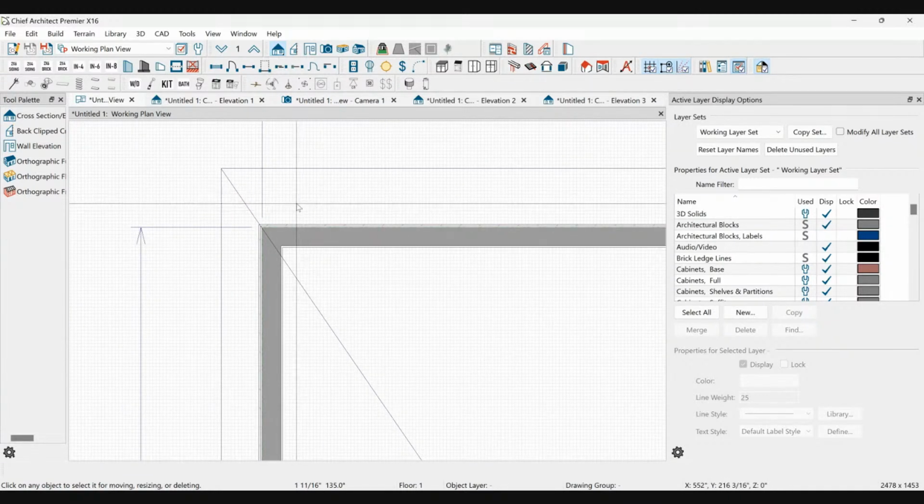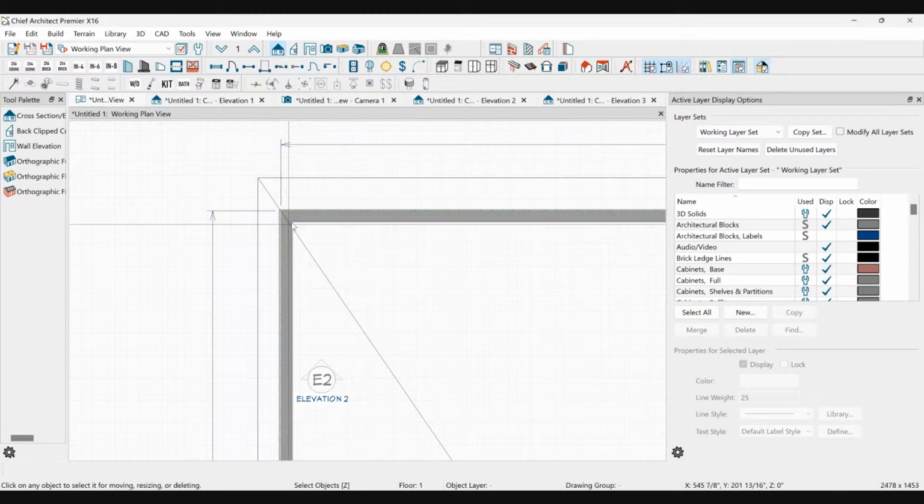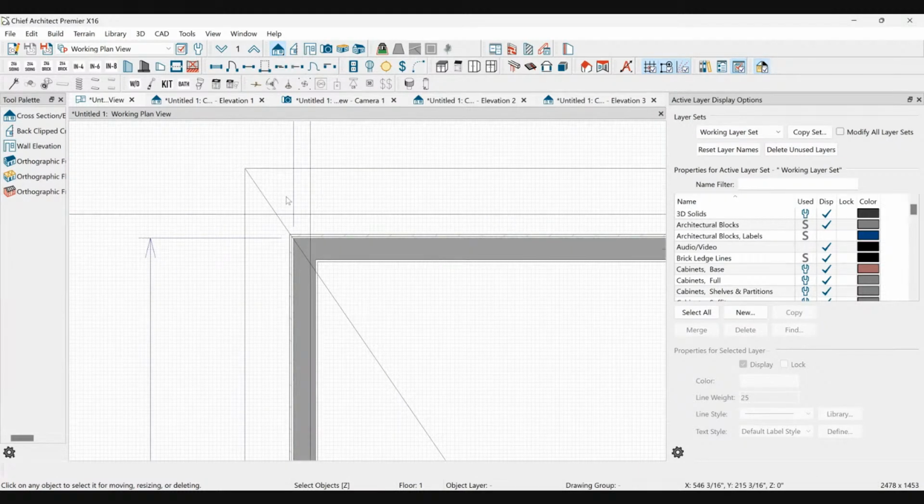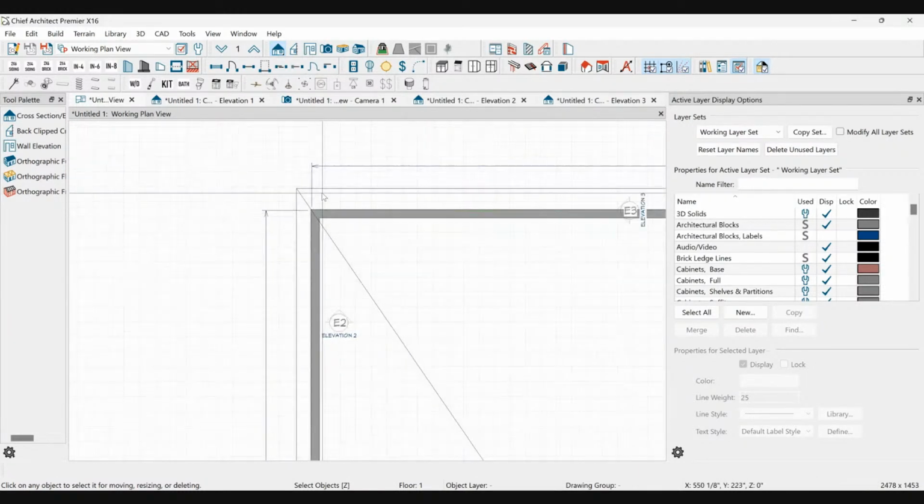You cannot have equal plate heights, unequal roof pitches, and unequal overhangs. So there's like 3 factors, okay? There's overhang distance, plate height, and roof pitch. Those 3 things will determine how corners come together like this and how soffits are built.